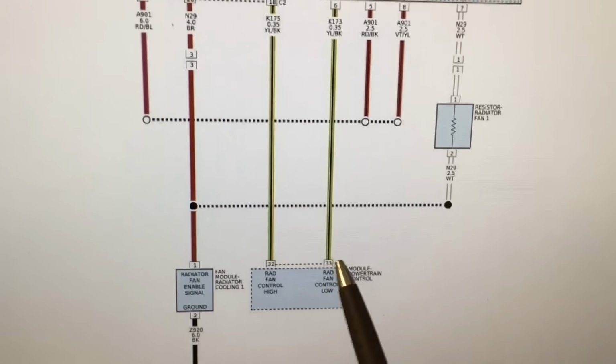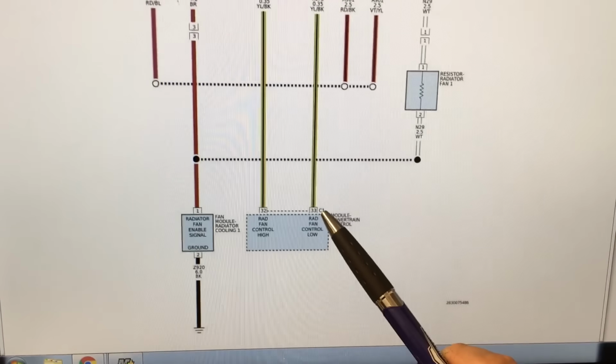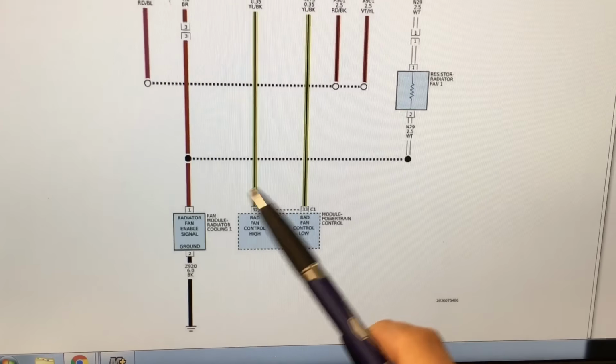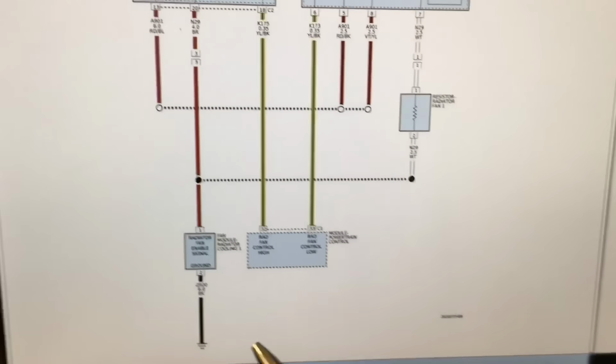Likewise, as soon as you turn the key on, there should be power that flows from the battery through this fuse, through this relay, and it should reach the PCM here. So with the key on, the computer is monitoring for a voltage here and also here. The problem comes when you turn the key on and the computer does not see power here or here.